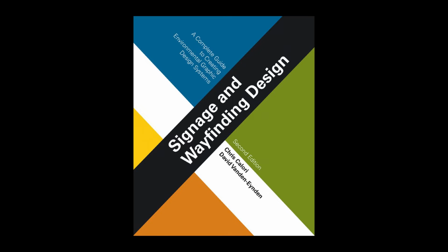Keep in mind that sign fabricators, lighting consultants, and lighting manufacturers can be useful sources of technical assistance on sign illumination. Externally and internally illuminated signs must be fabricated so that they are evenly illuminated with no so-called hot or cold spots.